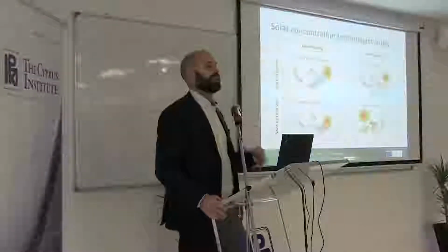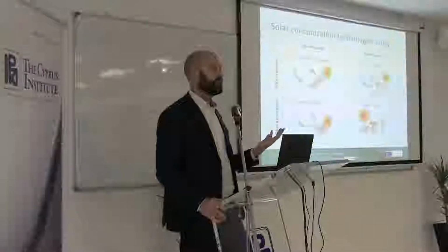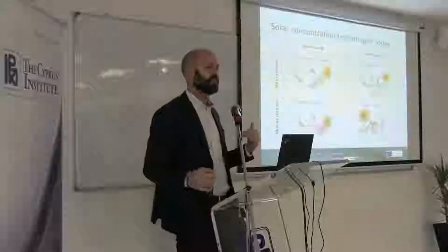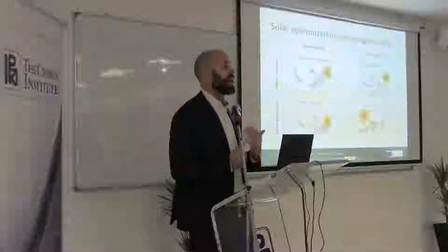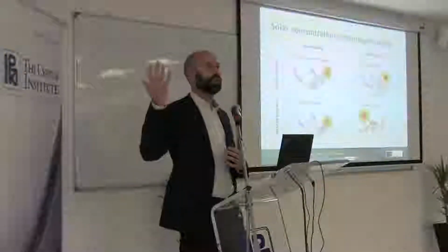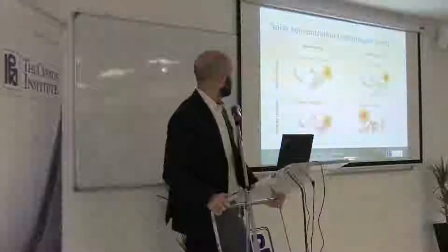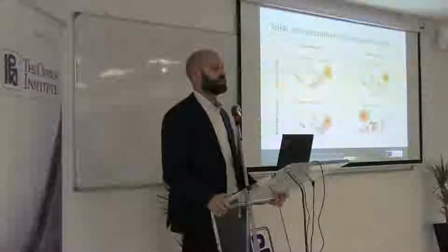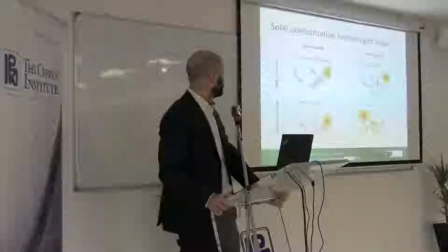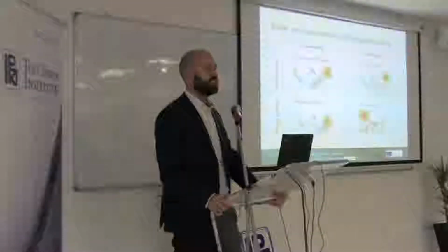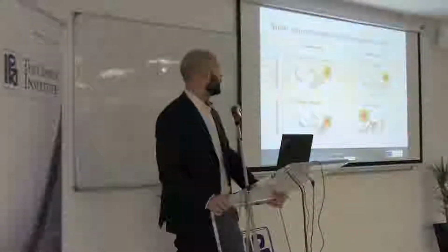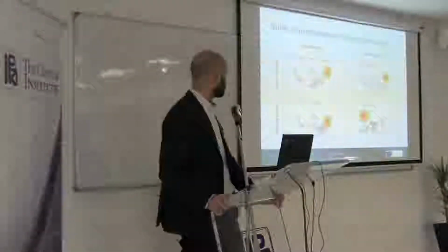So for point focusing, we can achieve very high concentration factors, even above 1,000. So we talk about 1,000 suns to say that the radiation is 1,000 times more intense, more concentrated over a surface than what we get directly from the sun. In line focusing systems, the concentration ratio is usually below 100, may go from, let's say, 70 or 80 for parabolic troughs, and even lower for Fresnel systems.